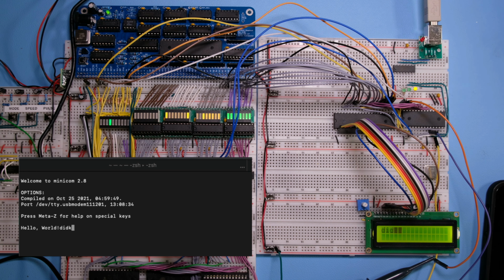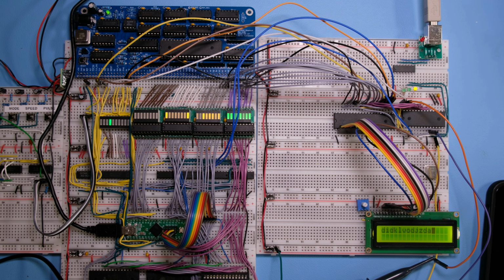There are a few things that we can improve with the design. Specifically, it would be nice if the computer didn't have to waste time waiting for bytes to be transmitted from the UART, and if transmission was interrupt based. And so we'll see in one of the next videos what workaround we can implement to be able to use interrupts with the W65C51N, and that's going to free up all those cycles of waiting.